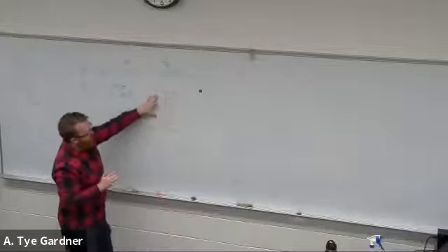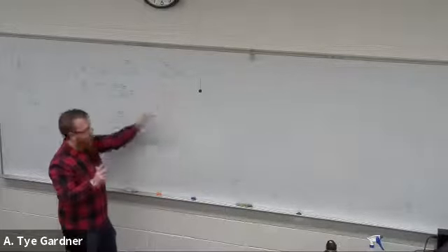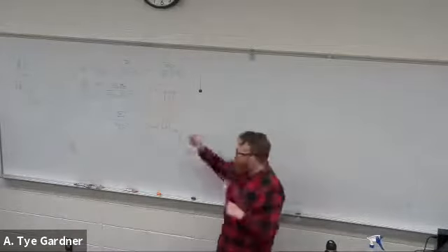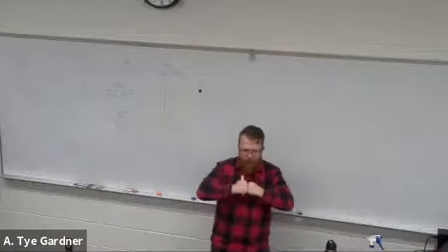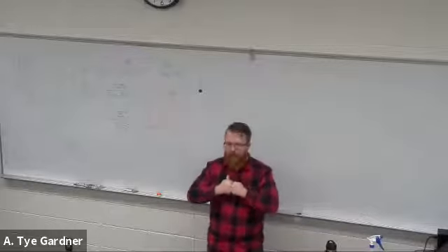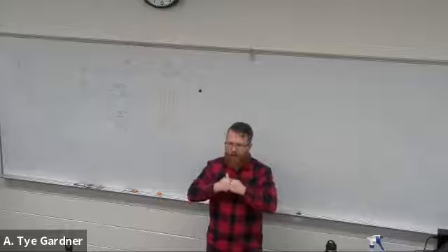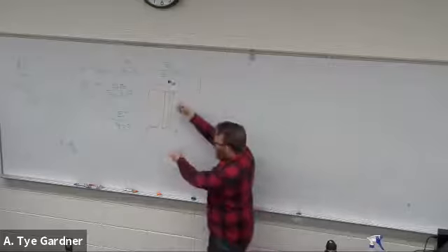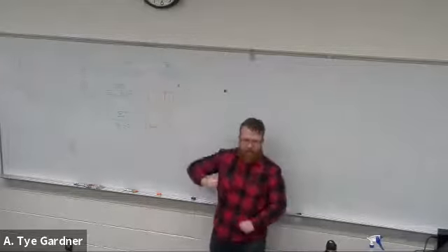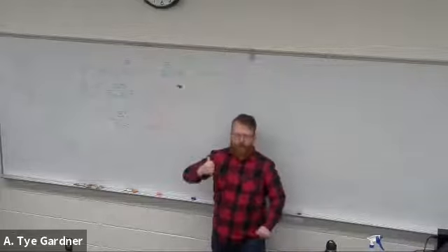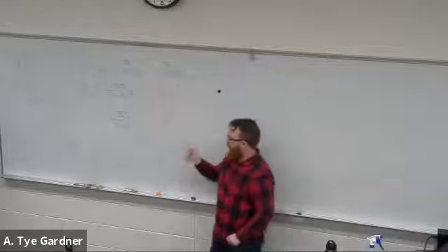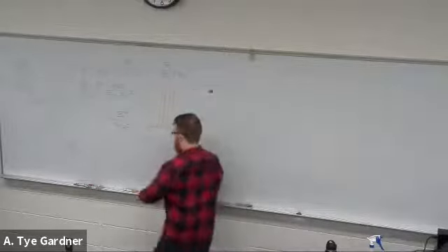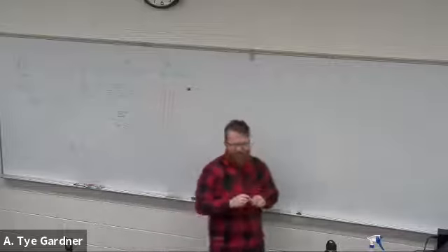What's going to happen is it's going to squish, crunching the conductor together, which in that case is going to lower the resistance because you're starting to push that material closer and closer together. It's easier for electricity to flow. Therefore, the conductance increases. The opposite is true when you grab it and stretch it out, right? So I grab the cylinder, stretch it out. The conductor is going to stretch with it, and it's going to become harder for conductivity to flow, and it's going to become more resistive. Now, unfortunately, and I'll probably end up bringing this up a couple of times, that change is actually very small.